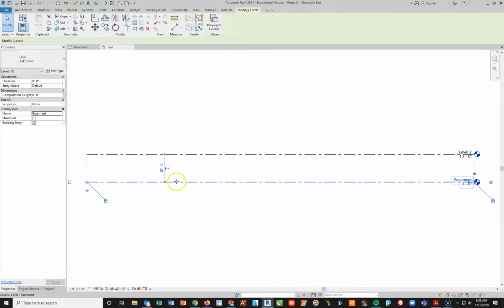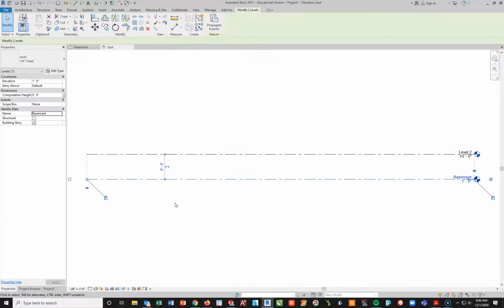Now I'm going to go ahead and have my basement be 10 feet, which is fine. Depending on your house, it most likely could be 9 feet. You figure a little 1 foot upper level, I guess. So I'm actually going to change this distance from 10 feet to 9 feet. And to make a 9 foot, you have to use the tick mark. So you use a 9 and then the single quotation mark. That means 9 feet 0 inches.